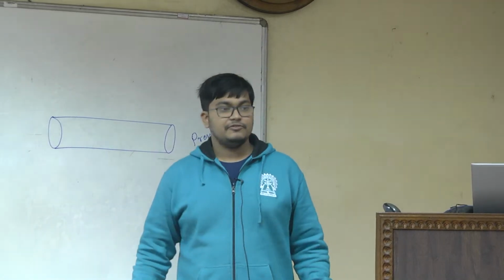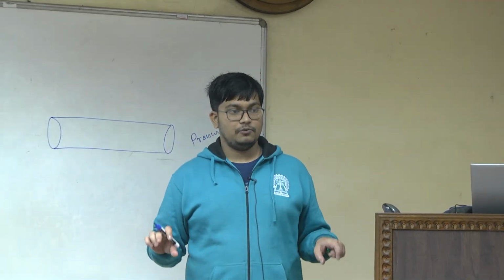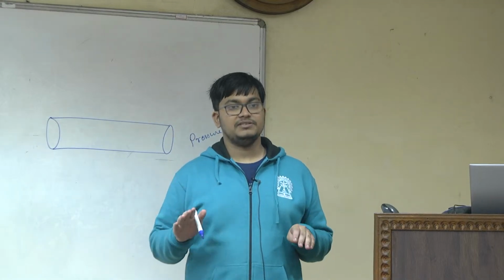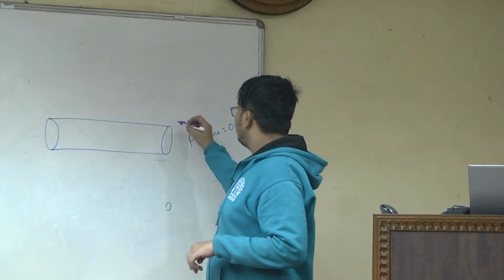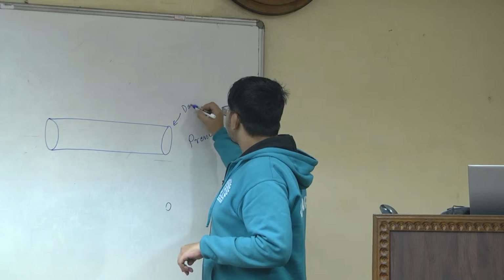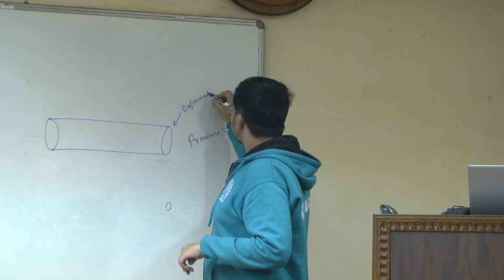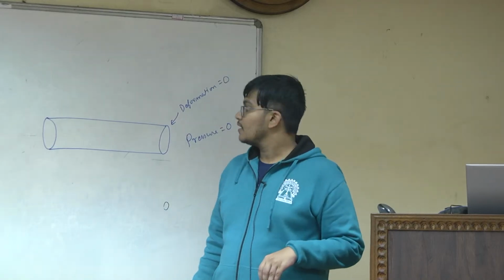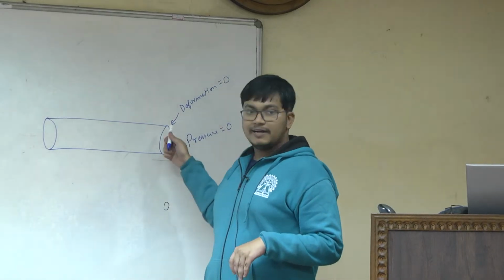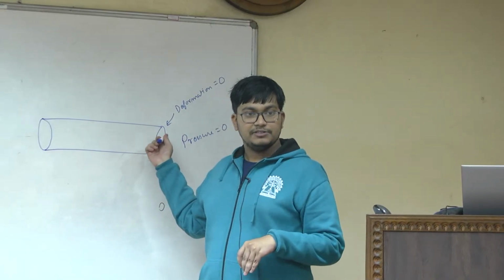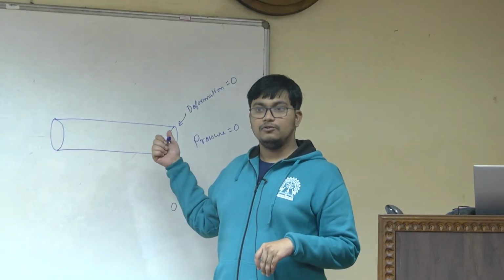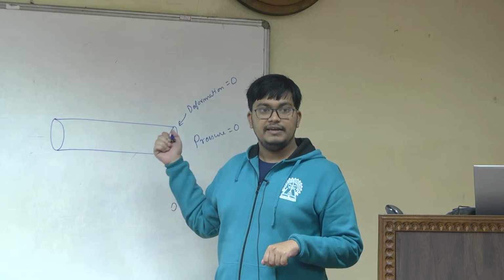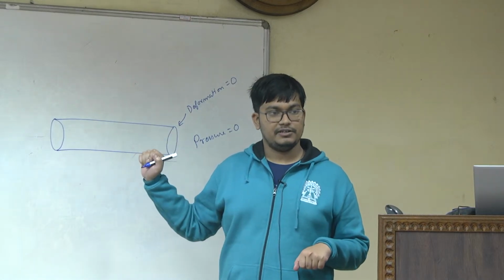When there is no pressure on the vessel wall, then the deformation will be 0. So here deformation is 0. But if we only prescribe on this wall the deformation to be 0, then Ansys will not be able to complete the simulation. Ansys needs another boundary condition.